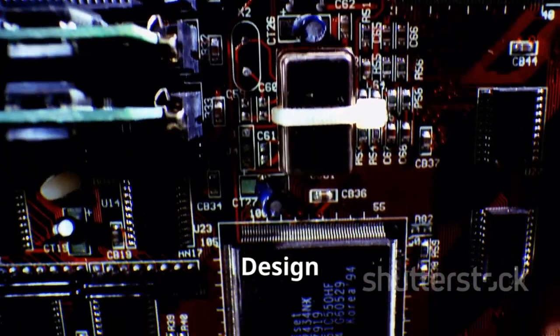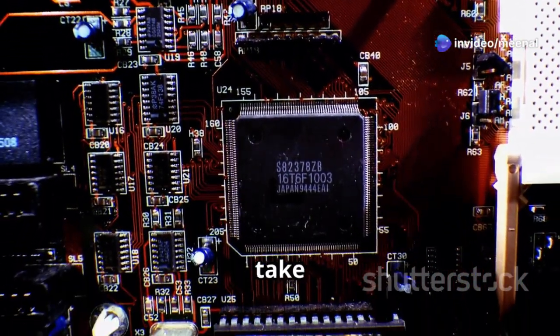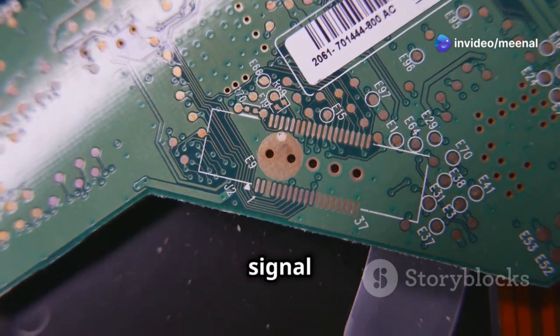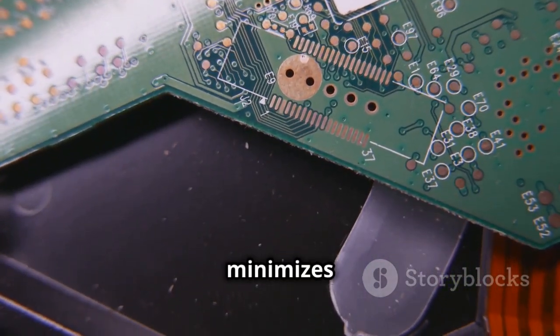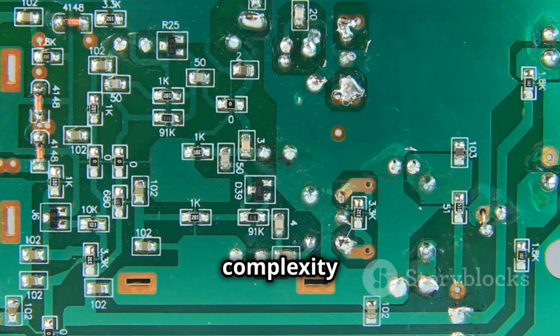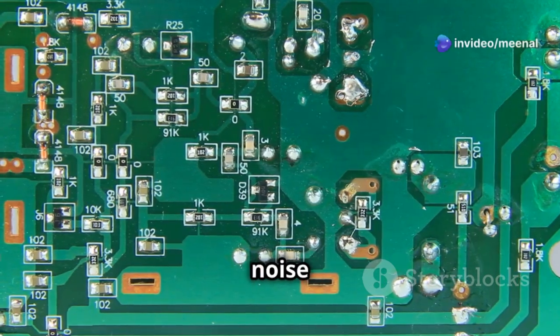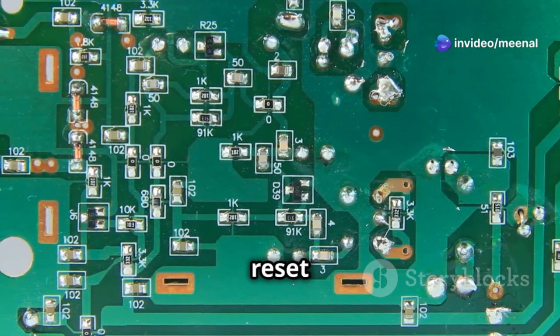Step 4. Design the reset signal path. This involves planning the route the reset signal will take on the PCB. Ensure the reset signal reaches all necessary components reliably. A well-designed path minimizes the risk of signal loss or interference. Minimize the length and complexity of the reset signal path to reduce noise and signal degradation. This is critical for maintaining the integrity of the reset signal.